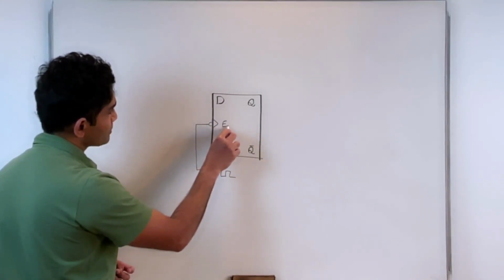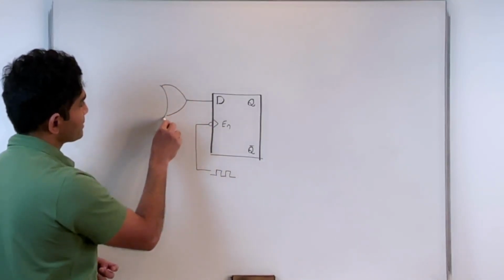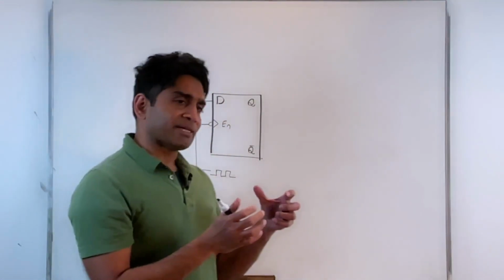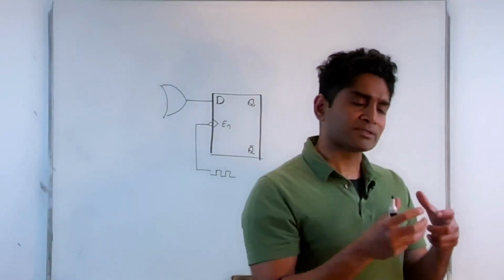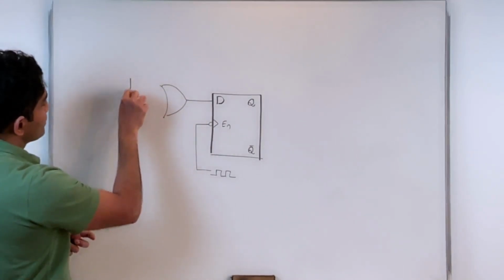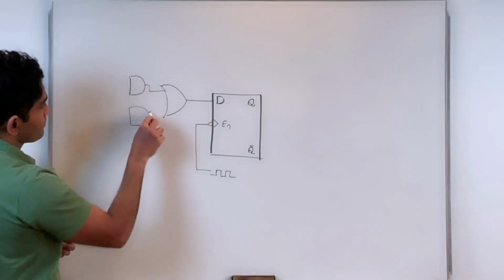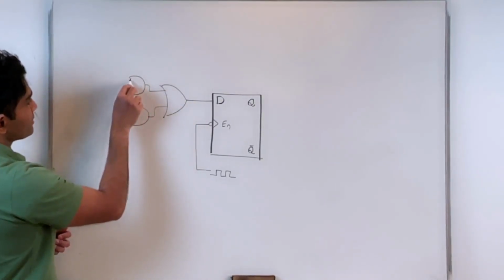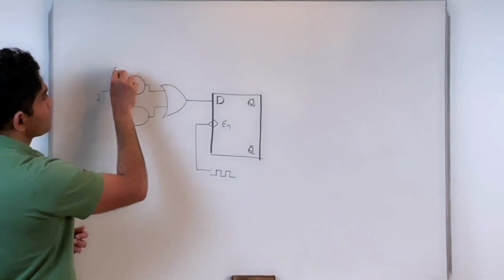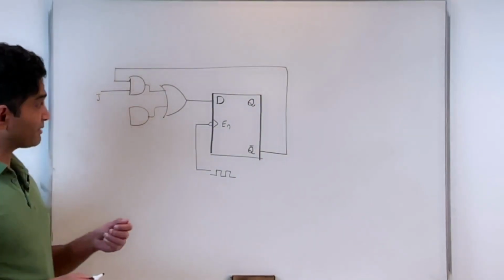That should enable input. And all I've done is basically use an OR gate here. In other words, I have implemented a simple combinational circuit, introduced a simple combinational block over here, introducing two new inputs to this system. One was the J input. Again, it features a feedback from the output of that flip-flop.